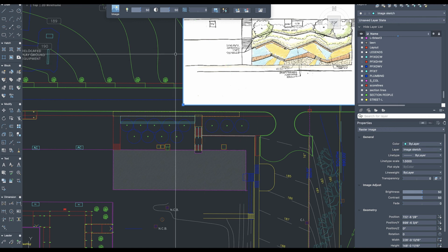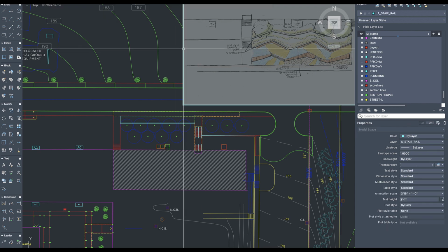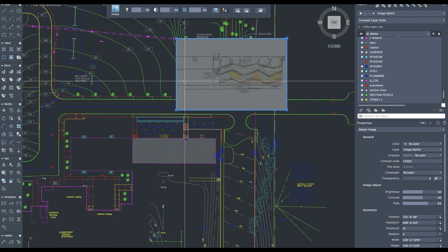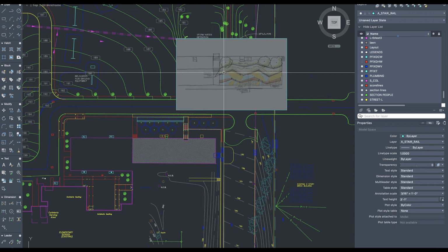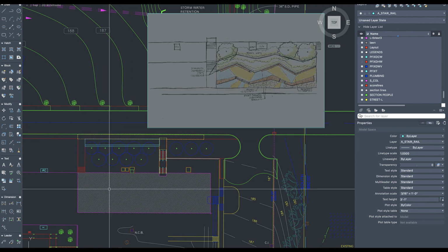Next thing we're going to do is turn down that sketch by double clicking on the image frame and bumping the fade up just a little bit. As you can see here, we've got to align this to the plan, so I'm going to move it over a little closer, or at least get it in my view, and find two common areas. Now, when I inserted this sketch, it's actually flipped upside down, but I know there are a couple spots that I want to align and scale in here to get it to our particular site.